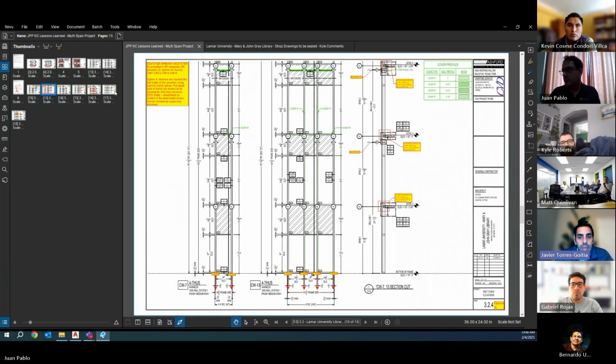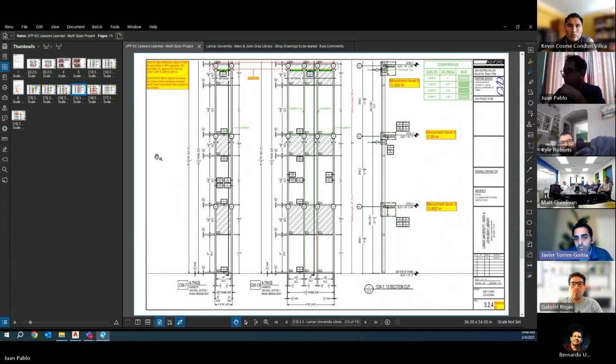And for option B, like when Pablo was saying, we basically bypassed the high movement areas with a wind load anchor, relocated some wind load and swapped some wind load for dead load, and moved the splices around a little bit. That option had the least impact as far as load transfer goes. So in that one, we didn't really need the EOR's approval. I just wanted to emphasize how important it was for this to work to get the EOR involved as early as possible.